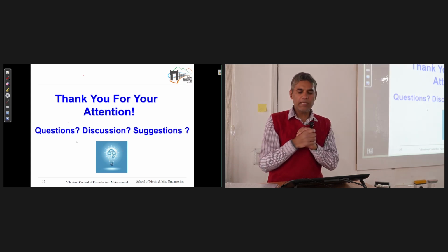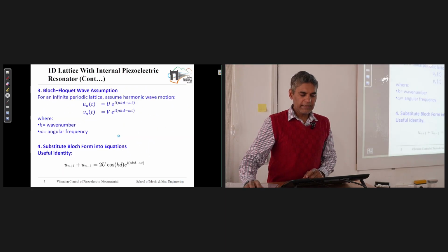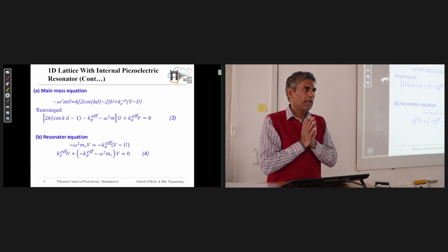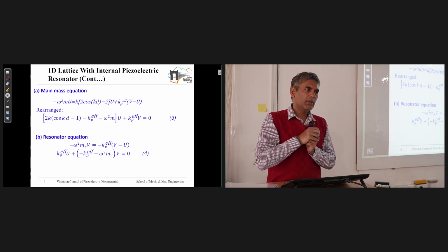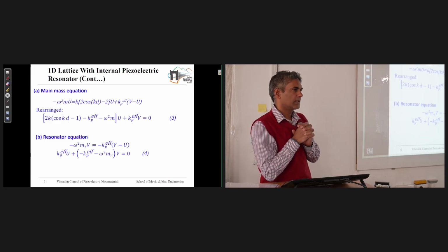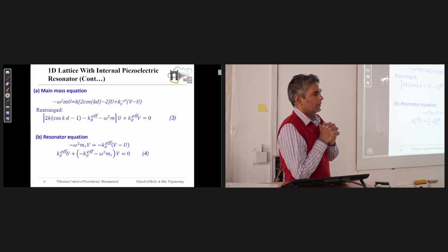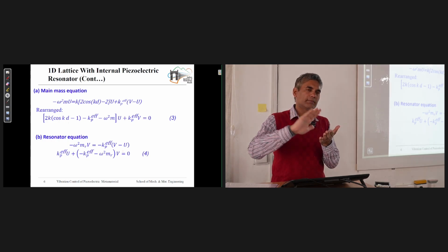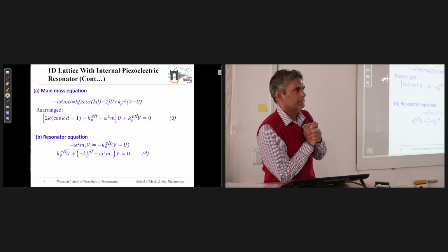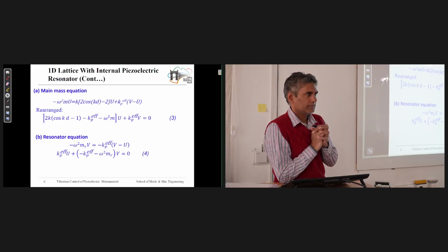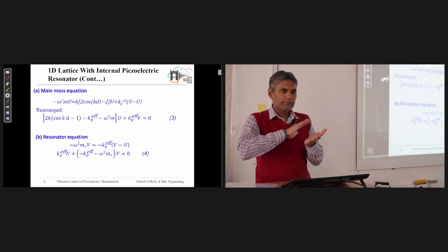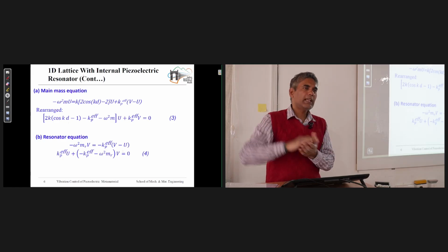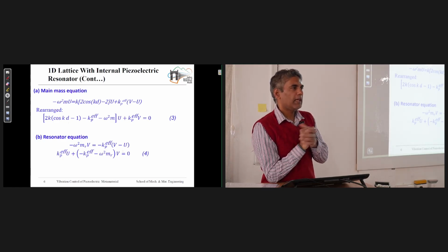Now see, in my discussions, if you noticed carefully, what I did, though it is not shown here, is that I used a plate and I inserted or embedded the piezoelectric material. If the piezoelectric material is bonded on the surface, then it will not be a metamaterial. Why is it so? Suppose I have patches, of course, and I have bonded them on the surface, then it will not be a metamaterial. It will be a metamaterial only if you have embedded it inside.